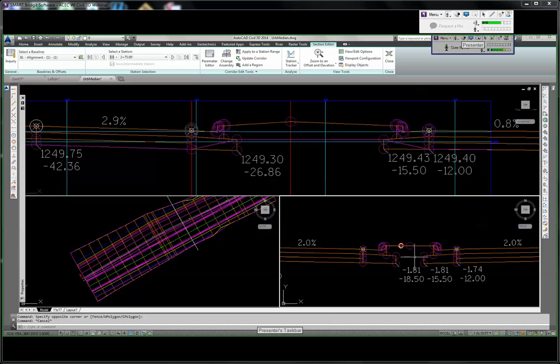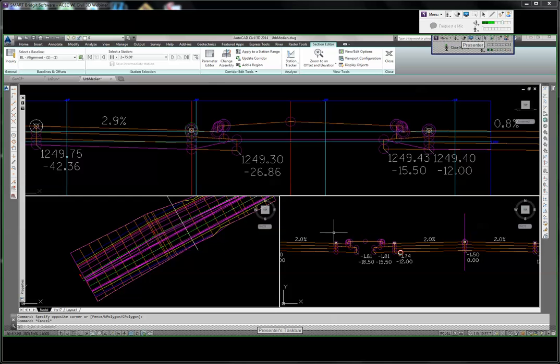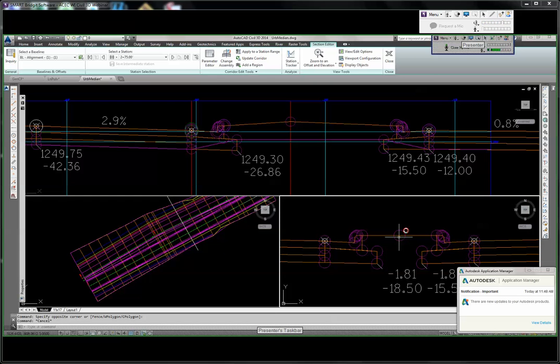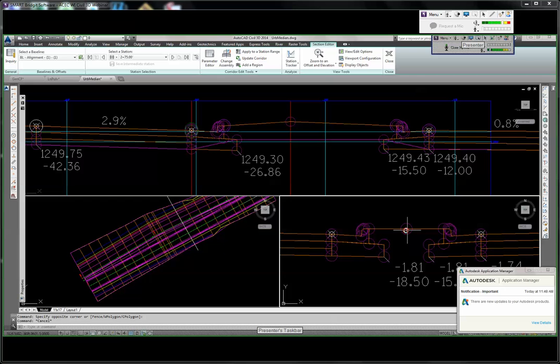So we're going to have to jettison that thought process and go into using this subassembly from its original assembly. So everything is attached to this assembly here, and we're always moving to the left. But this curb and gutter still needs a marked point out there so that I can widen it. You saw how, as I advanced, the median got wider. Well, that's because I have a marked point employed. I just have a kind of a fancy way of doing it. It's very difficult to show here, so I'm going to sketch out what I did and explain it.